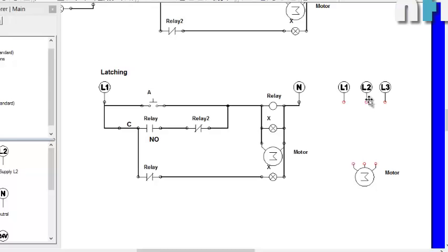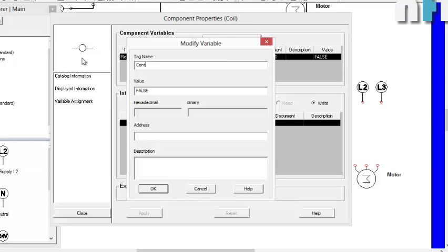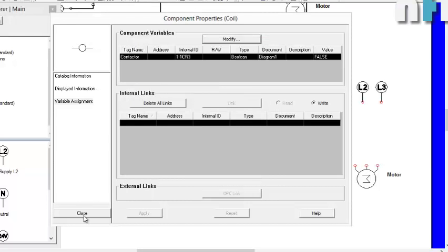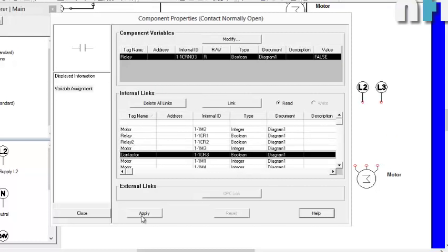And to connect this line 1, line 2 and line 3 to the motor, we need 3 more NO contacts of this coil. Now it must be noted that if you are connecting a 3-phase motor, you will never use a relay. We use another device which is called a contactor. Actually both relay and contactor work on the same principle, but they are named differently because a contactor is typically used for 3-phase supplies, when you need to provide 3-phase supply directly to some device.